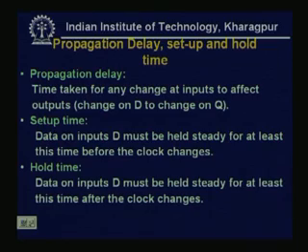But before that, we will see what we mean by propagation delay, setup time, and hold time, and how these times affect the actual value at the output line. First, propagation delay is defined as the time taken for any change at the inputs to affect the outputs.